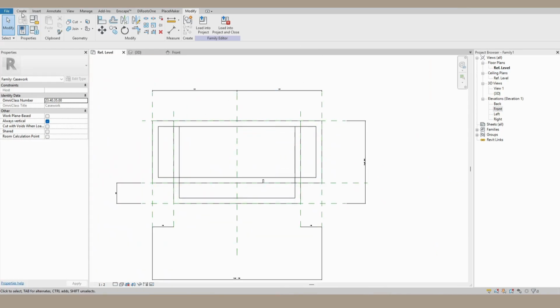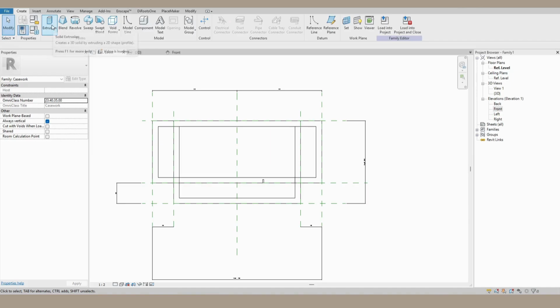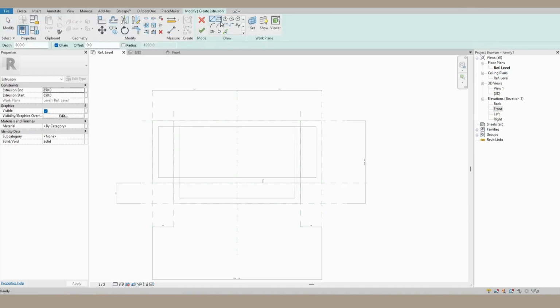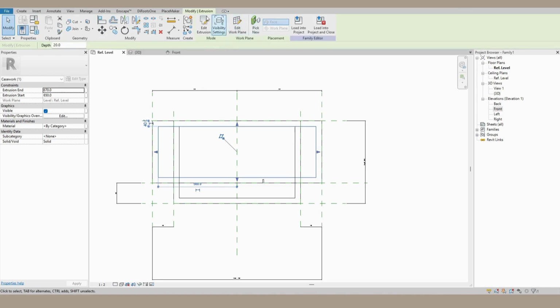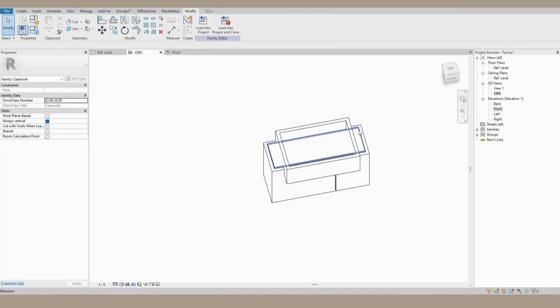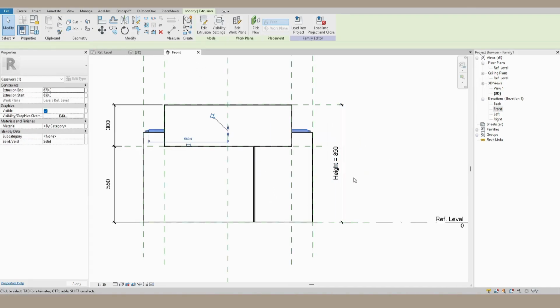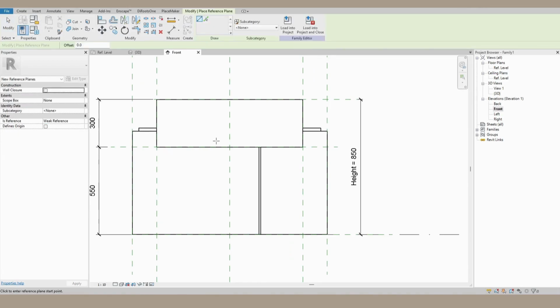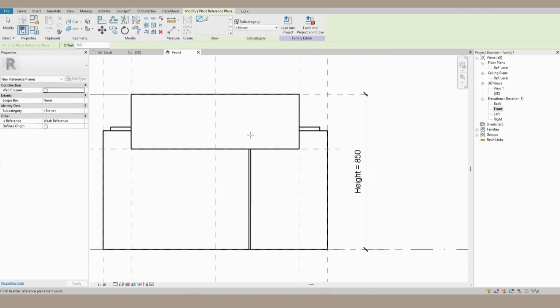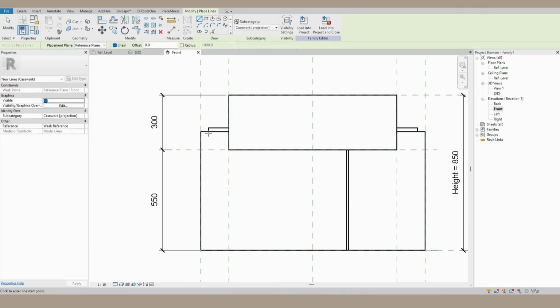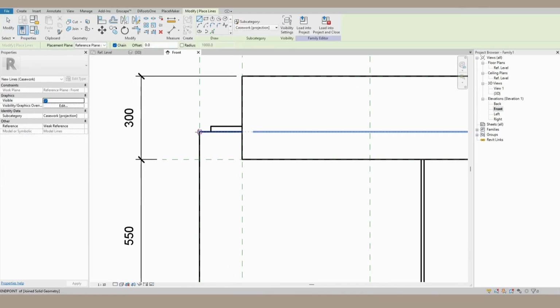However, in some instances, if you do want to model some basins, or you want to model some sanitary items, you probably do want them to be wall-hosted, wall-based families. However, as an interior architect, I find that a bit constraining, in terms of, let's say you want the basin to be the centerpiece of the room. Now you need the wall there as well. So I'm thinking this is a lot easier to work with for now. If anyone knows a better way, please definitely comment down in the section below. Let us know, and we can explore all the options.